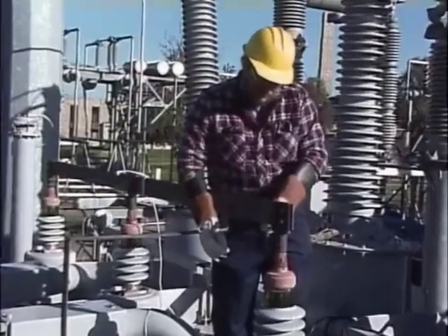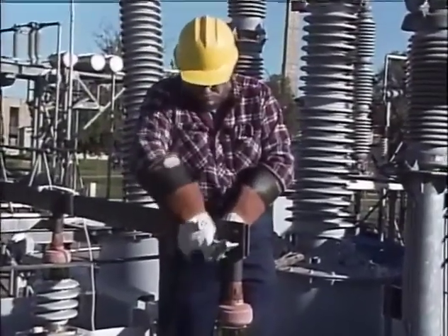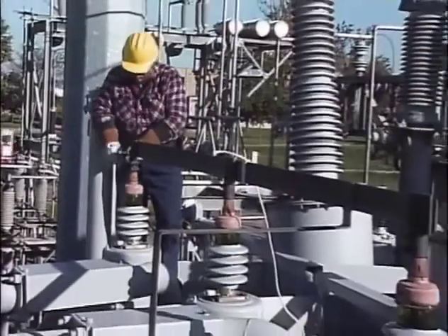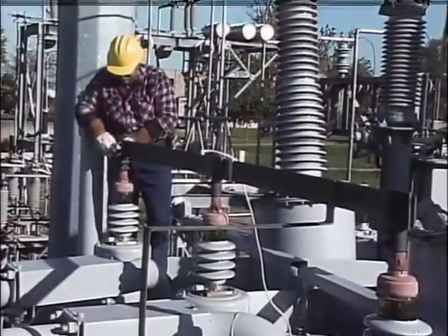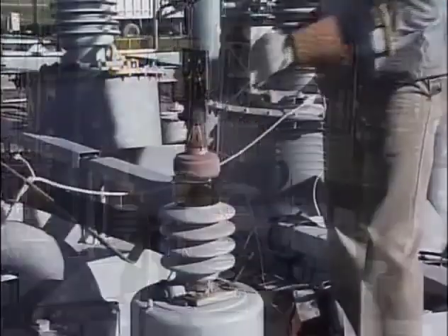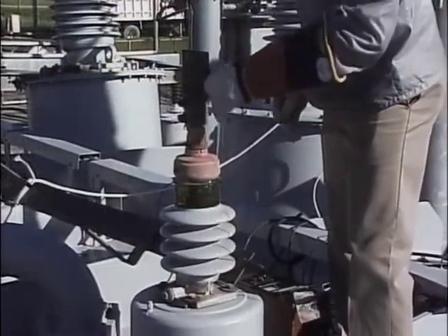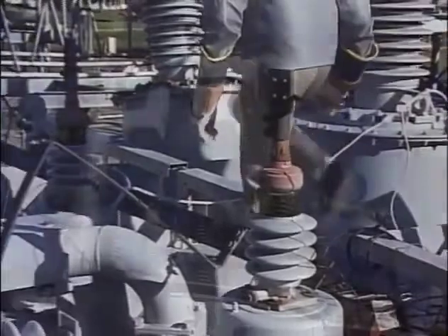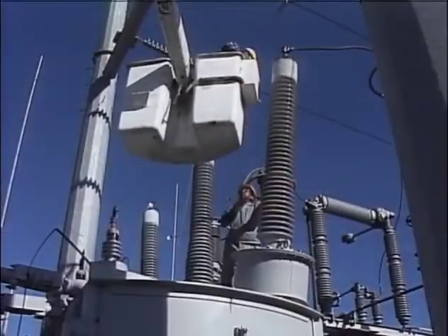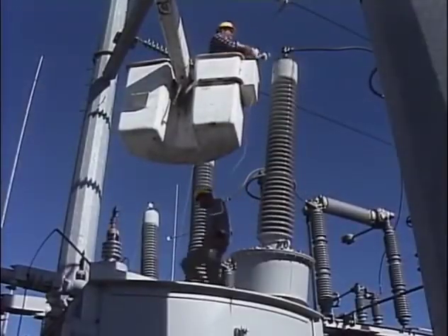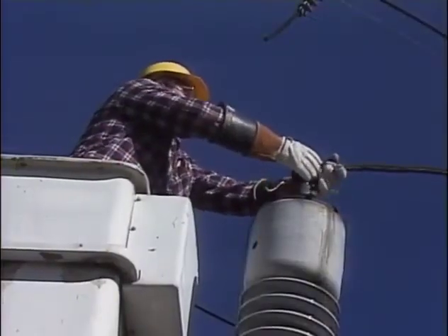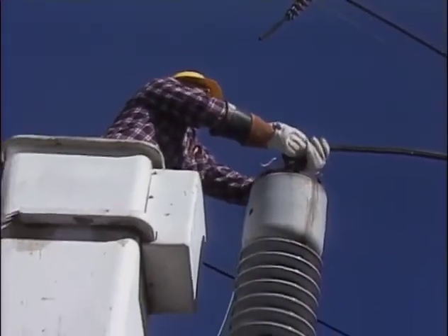On a shunt reactor, the insulation is tested one phase at a time. So for this reactor, a bar that ties all three neutral terminals together must be removed to isolate the three phases. As a safety precaution, each of the neutral terminals is individually grounded until the test is performed. Next, the neutral and source terminals for each phase of the reactor are shorted together, and the source leads are disconnected from the reactor source terminals.